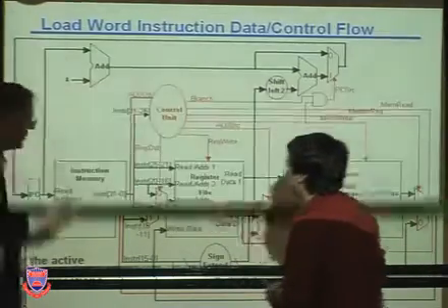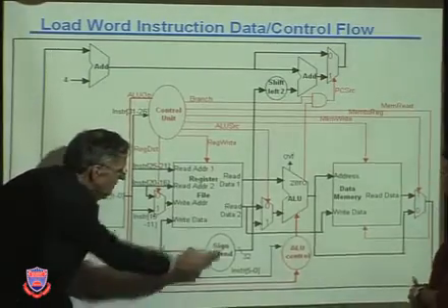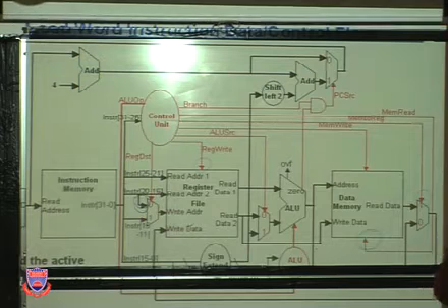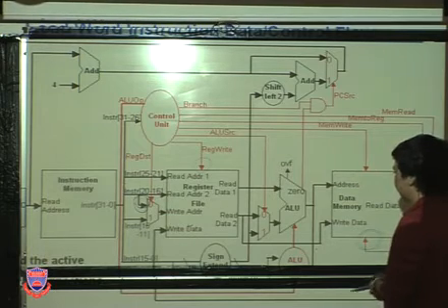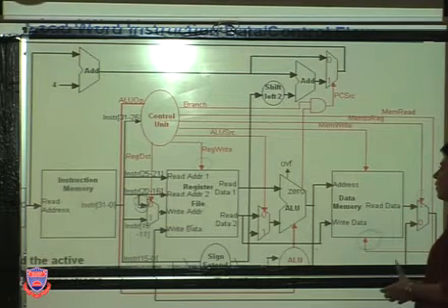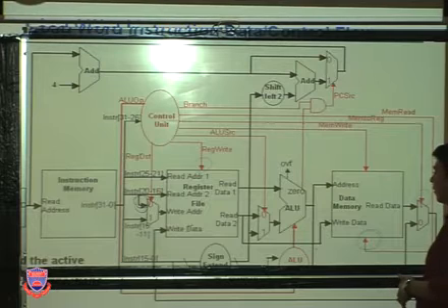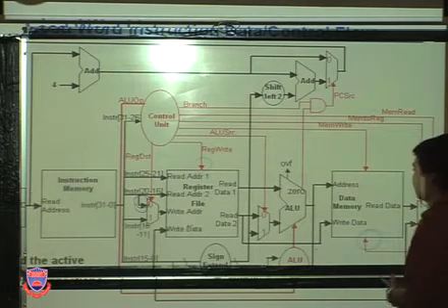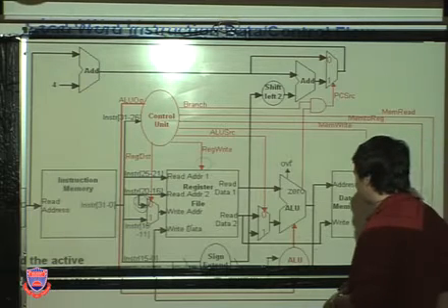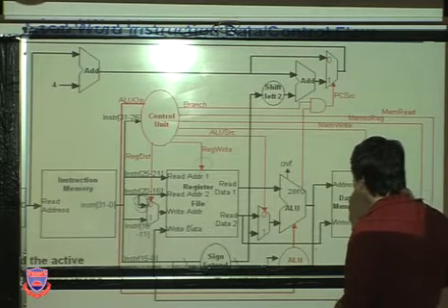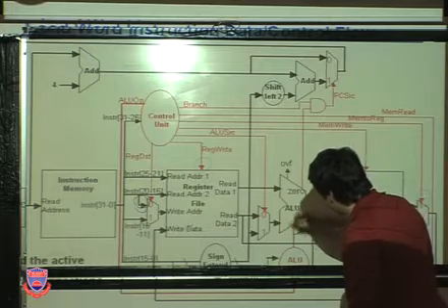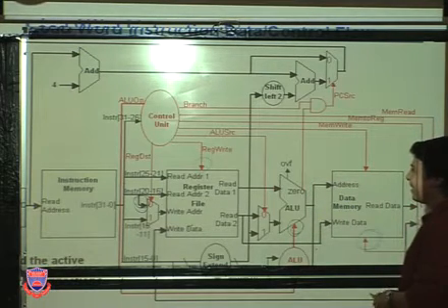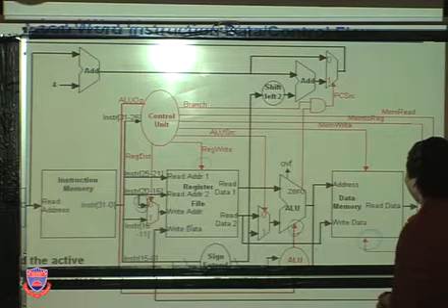Okay, there's another one here. Well, that's always sign extending. No problem there. What about ALU control? What are we doing with the ALU? What do we want the ALU to do in a load operation? Add, right? We want the ALU to add two things. So make it add. Yeah, that matters. Okay. And keep looking. Is there anything else there?